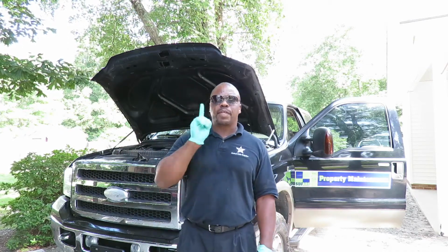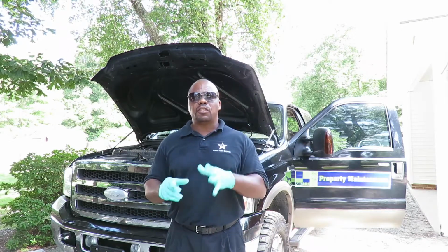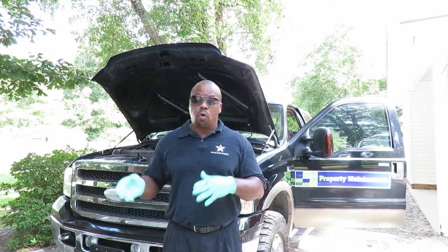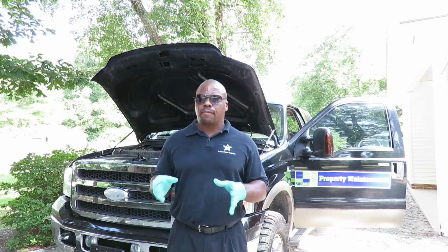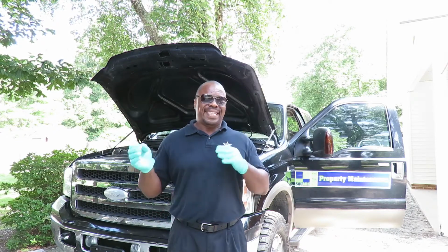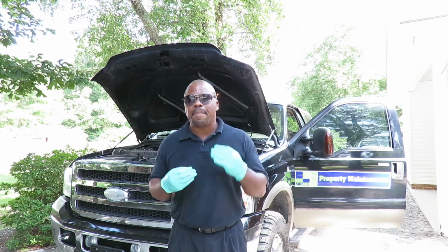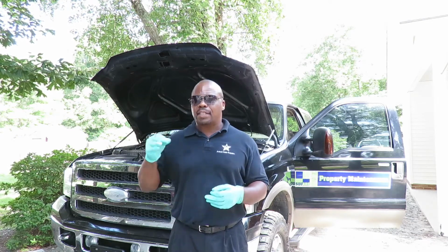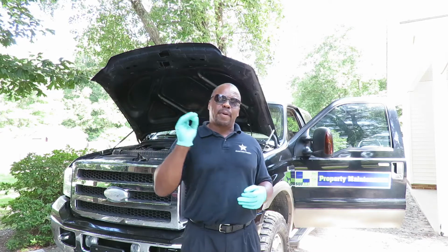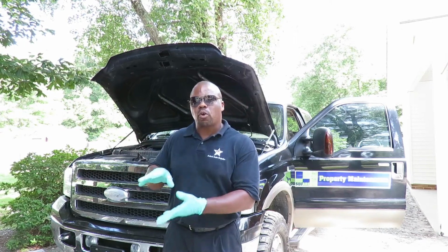First thing and foremost you want to do is, even if the check engine light is off, check out what the computer is sensing. If the computer picked up a code, maybe there's a pending code, and a pending code will not trigger that check engine light. So no matter what, that's the first basis. You want to start there.